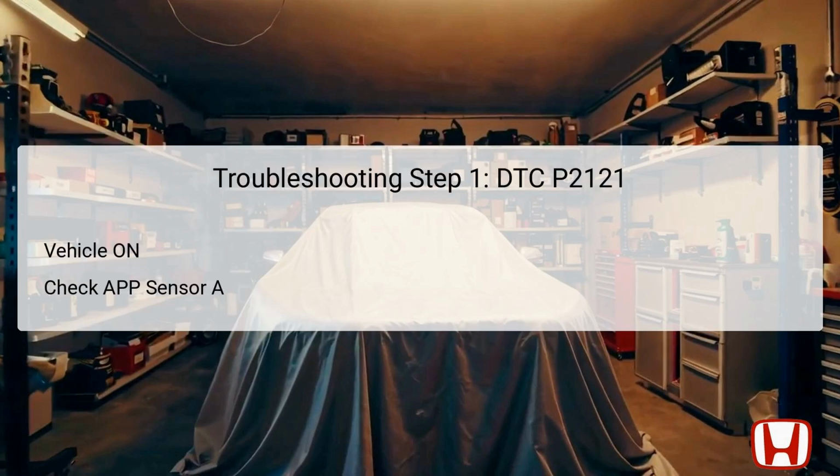In the first troubleshooting step for DTC P2121, the vehicle should be turned to the on mode. This is crucial as it powers the vehicle's electrical systems, allowing diagnostics to be performed. With the Honda Diagnostic System, HDS, connected, it's necessary to check the APP sensor A to review its current reading against established thresholds.